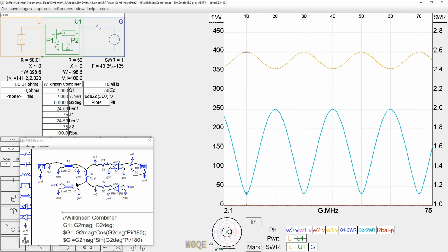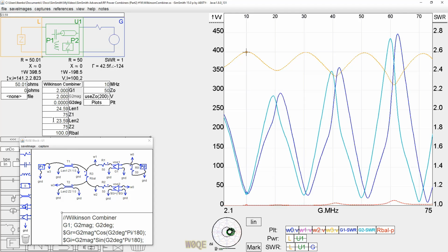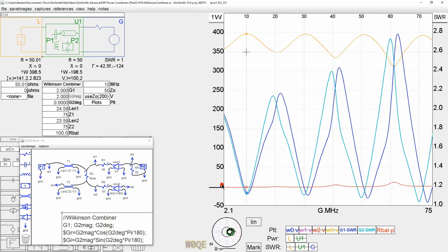One thing you might be a little bit careful about doing is when you build this circuit up, you need to size this resistor really carefully for fault conditions. So anytime we do anything that imbalances any of these parameters along the way, we will start to see there'll be some power down here. So you won't be able to get away with a tiny, tiny little resistor if you choose to include that component.